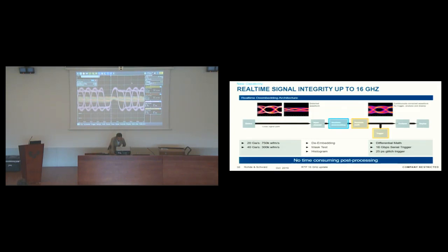So I'm going to apply de-embedding. This block here takes me to the de-embedding block. I will preset. What we have here is the basic configuration, just the DUT and the input. So in this representation, what we have would be like a direct connection.